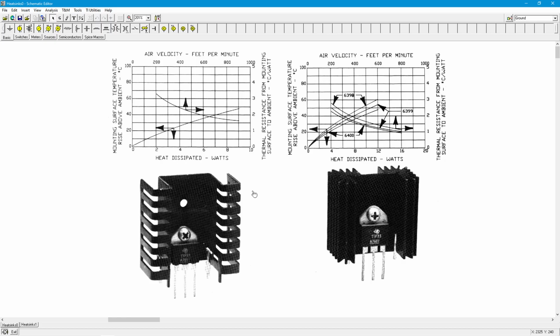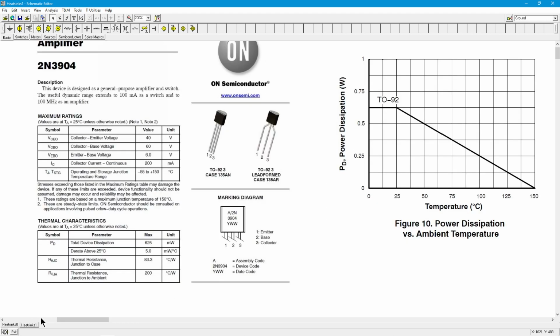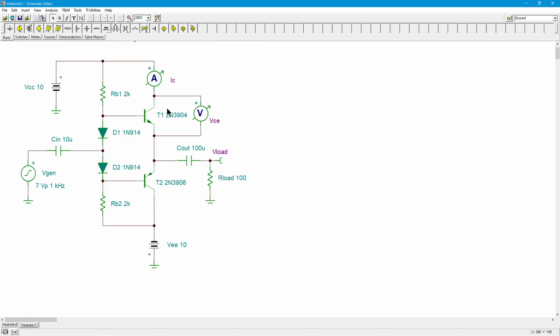Oh, by the way, before we call it quits, you can buy heat sinks that are designed for multiple transistors. So don't think you just buy a heatsink for a transistor. So that original circuit that we were looking at, if this was scaled up in power, and these were not an 04 and 06, but like a 3055, something big, you wouldn't necessarily have one heatsink for this and one heatsink for this. You could have one heatsink, and they're both bolted to that.